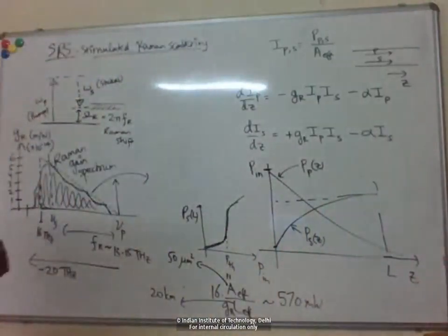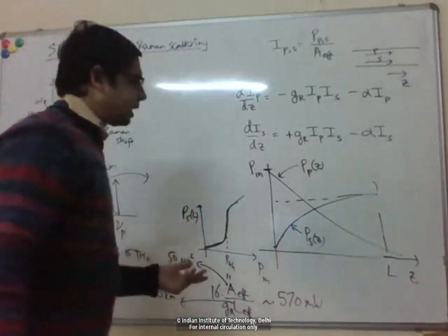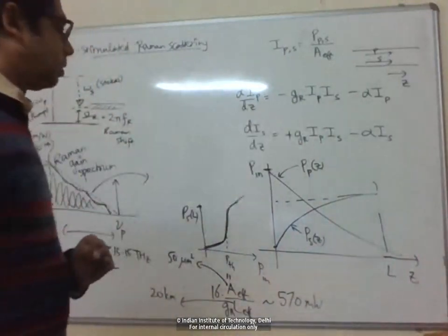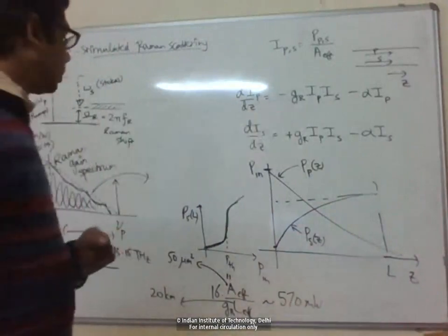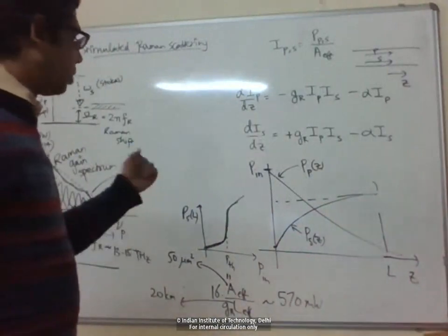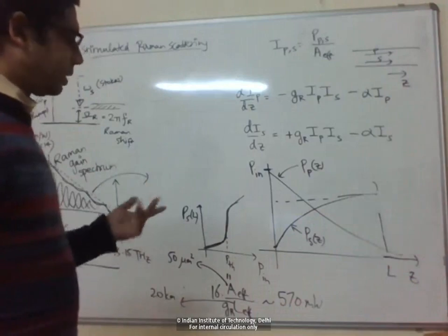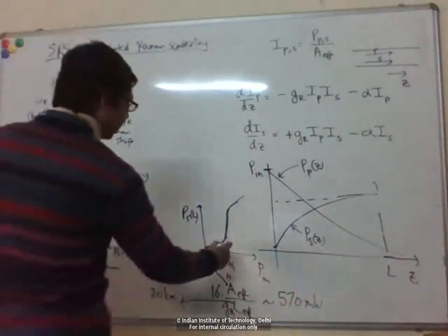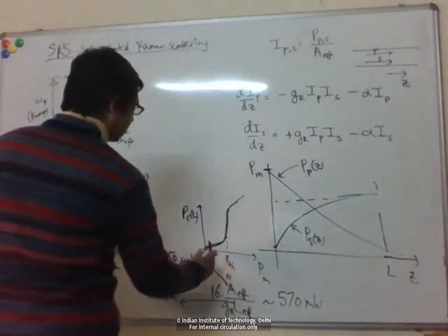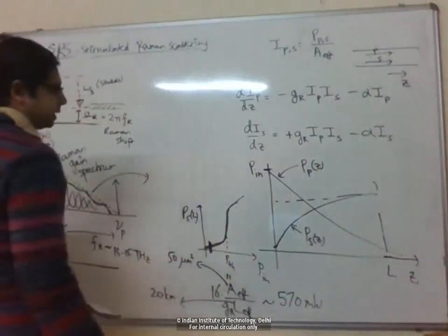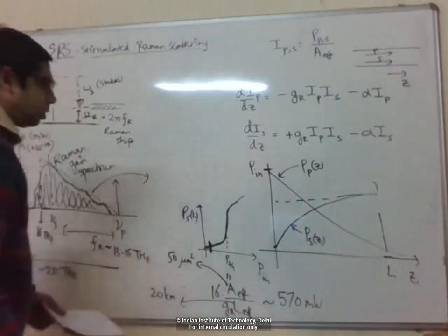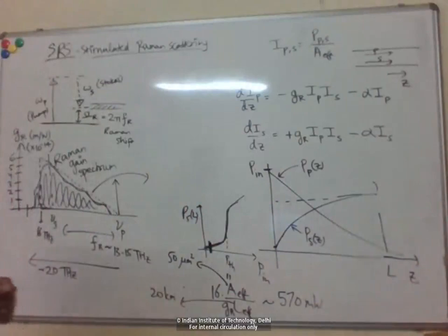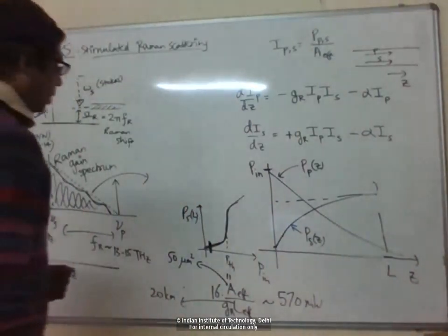So basically what this is saying is, let's say I have only one channel propagating through my fiber, then the loss that I get due to Raman scattering is negligible if my powers are in the tens of milliwatt. So if this is 500 milliwatt, usually I'm operating here. So the loss to the Stokes is very negligible, right?